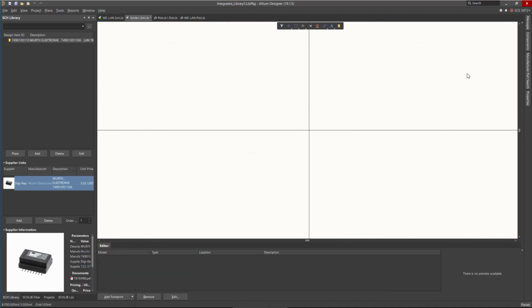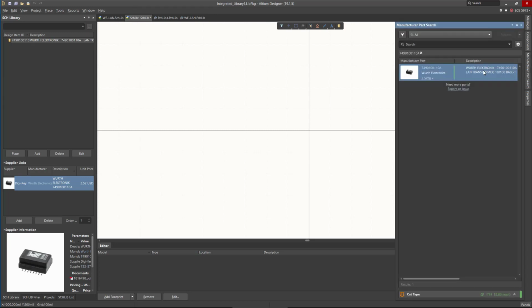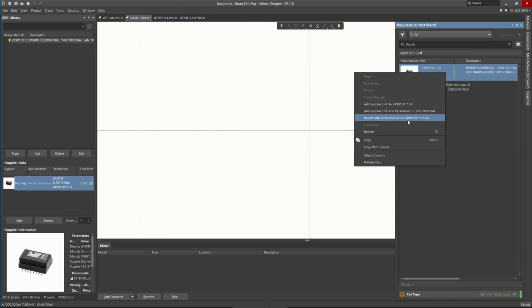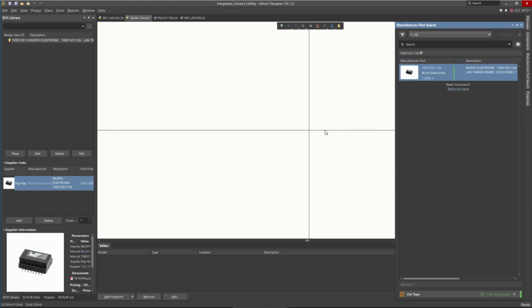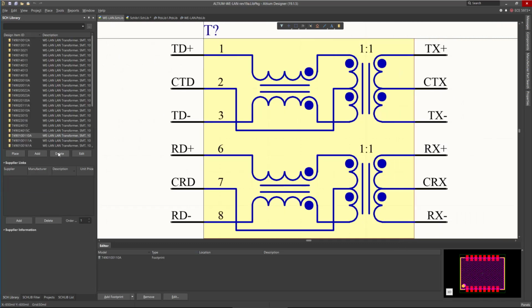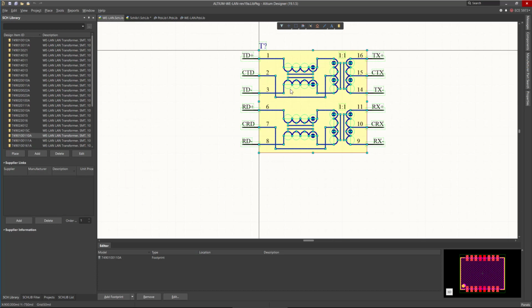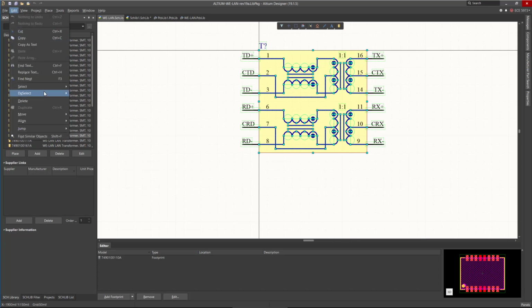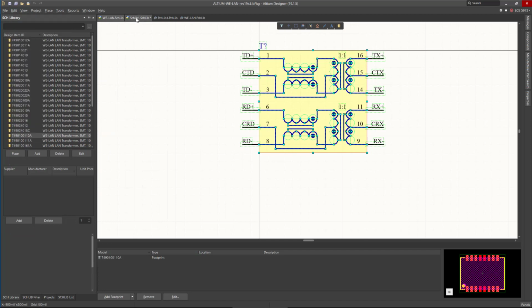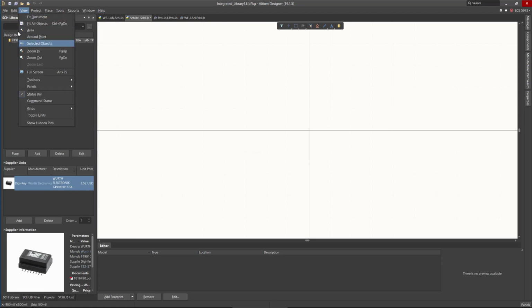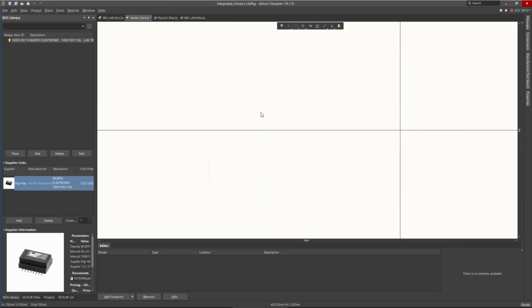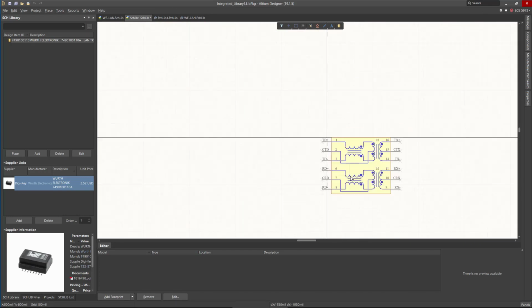So this is done. This is the first step. Basically, you imported all the parametric data into the schematic library in one click, just one click. Right click on it, import. Everything is moved to here. Now the next step, you go to the vendor library, and this is basically the components I want. So copy this symbol, select all, or you can go to edit, select all, edit, copy. Now go back to your library in here and edit, paste, and place this component.